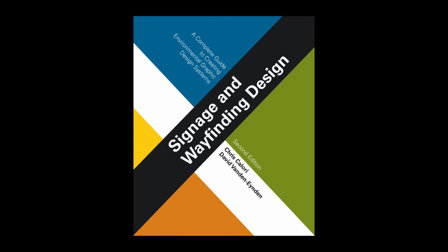Wood. As sign materials, wood and wood products are less commonly used today than they were a few decades ago, having been replaced to a great extent by new materials on the plastics front. Nevertheless, products made from wood, such as particle board, are still used for some signage, including sign faces and plaques, as well as for lightweight structures. Wood products come in both structural and sheet forms, from cheap pine 2x4s and plywood to fancy lathe-turned posts and exotic solid hardwood or veneered panels.